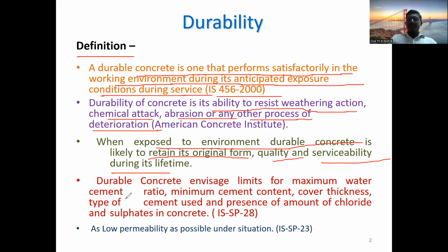Durable concrete needs a limit on the maximum water cement ratio, a minimum cement content, then cover thickness, type of cement used, and the amount of chloride and sulfate, as per SP28.